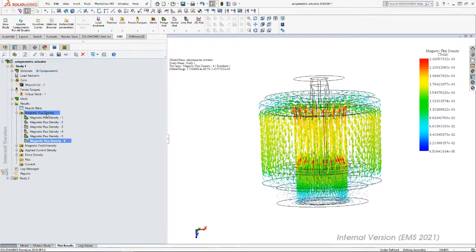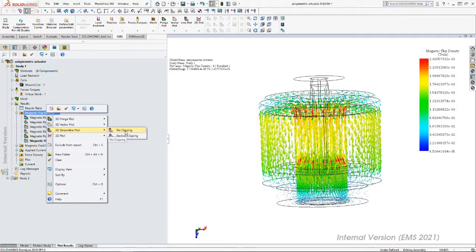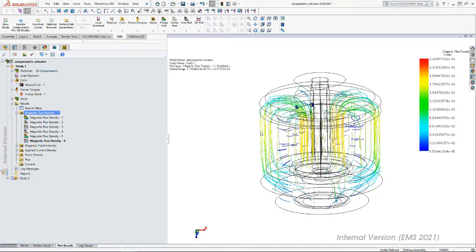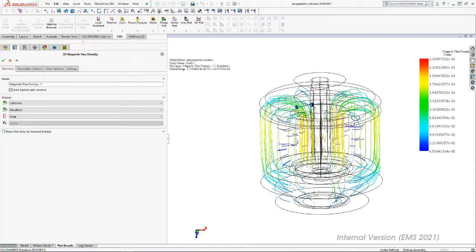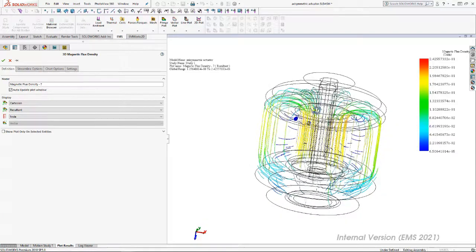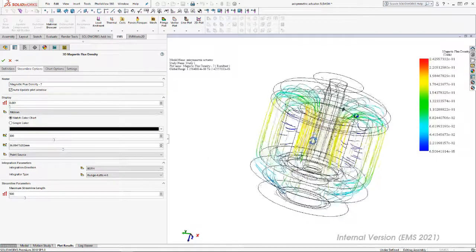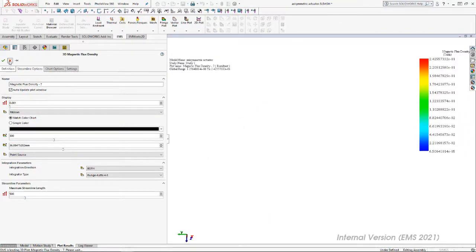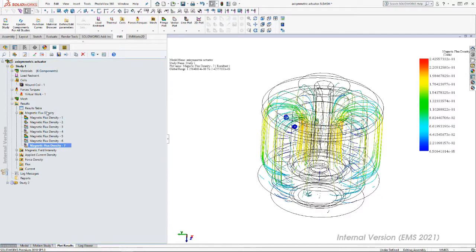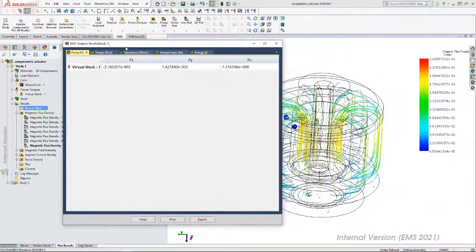and we have this option of streamline, one of the most interesting options. We have the field lines here. As you can see, these are the magnetic field lines. We have some options here to play with these lines. Okay, so this concerns the plot results, and we have the tabular results. They should contain results related to force, torque, inductance, resistance, and so on, related to the coil.